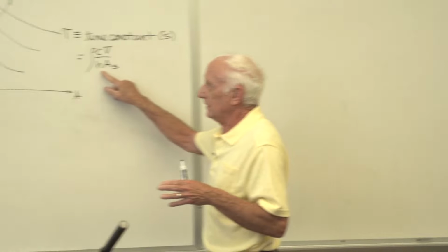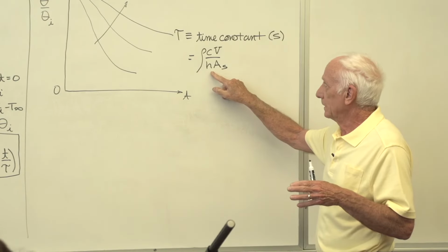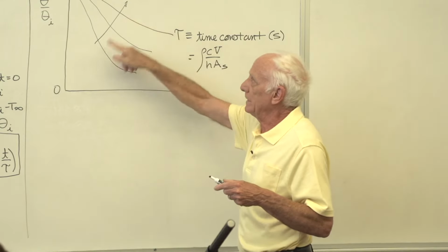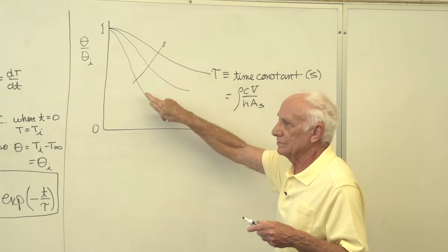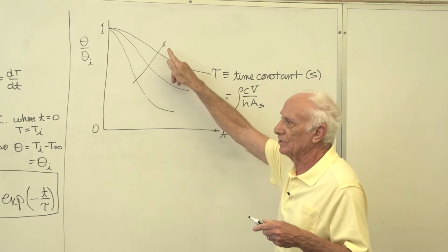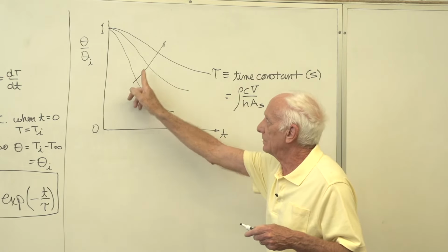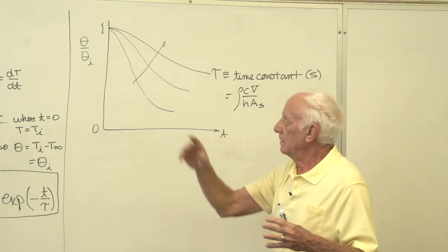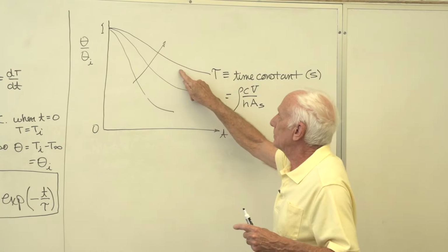h is going to be really low. Time constant is going to be really high. This arrow means high time constants, low time constants. The direction of the arrow tells me increasing time constant curves this way. So, copper sphere in this room, it cools real slow.